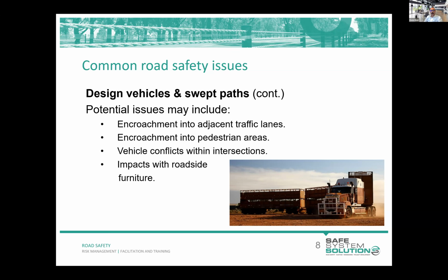So what's an example of that? Would it be like a removalist truck in a residential street? Would that be like a checking vehicle? Probably it would be your design vehicle, and there's an Austroads guide that sets out some typical combinations of design and checking vehicle requirements for different intersection scenarios.